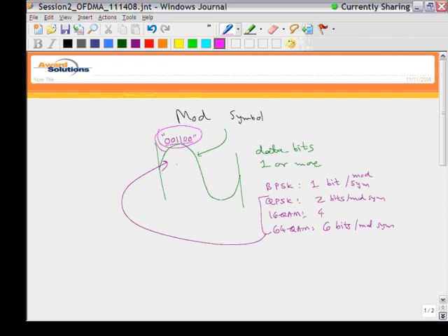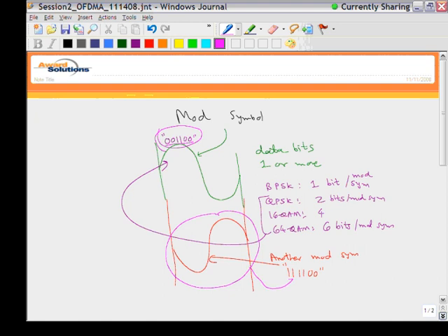Okay. So the meaning of each type of waveform is predefined in the standard. If we have another kind of waveform, something like that, this may represent another modulation symbol, and for example, it may correspond to another pattern, let's say 1, 1, 1, 1, 0, 0. So the standard defines exactly how to interpret the received signal structure. Depending on what kind of waveform we get, we know that it corresponds to a specific set of bits.